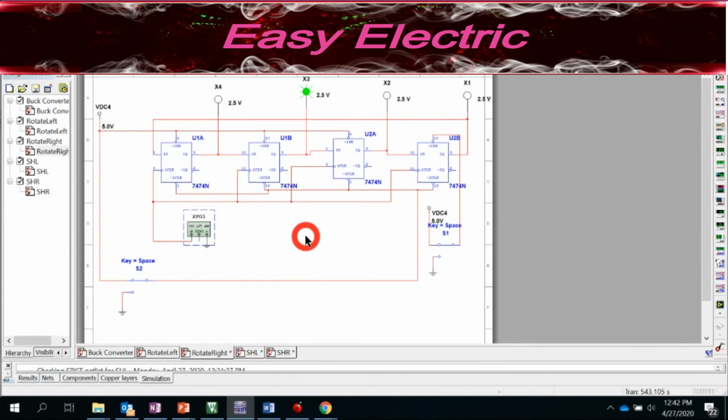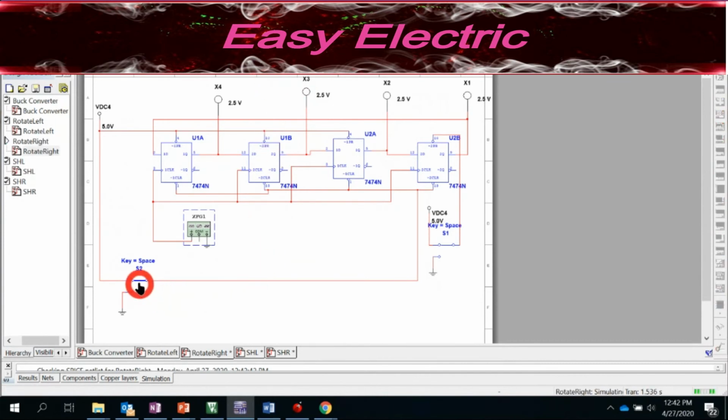So this is the same design we just implemented in the simulation. We simulate that again, similar to all the previous shift registers. We use this initialize, put that 0 back to 1, so that I make everything 0. So it circulates, but because the whole thing is 0, we couldn't see that. So I'm going to activate this preset for a short time to make the one, so that I am able to see how that one moves inside this shift register. I put that 0, it's gone, then I deactivate that.